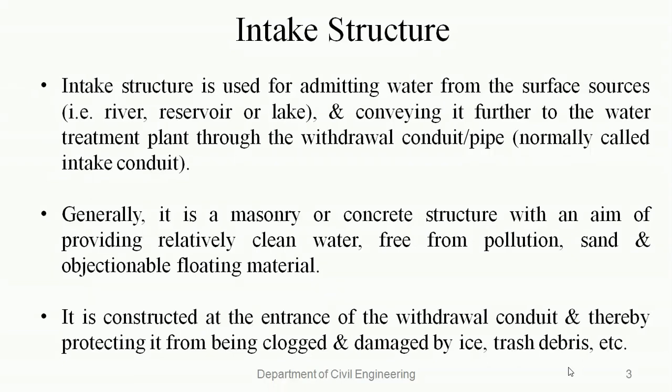After collection of water, the next step is to convey it further to the water treatment plant with the help of a withdrawal conduit / pipe, which is also known as an intake conduit. An intake is generally a masonry or concrete structure constructed with the aim of providing relatively clean water, which is free from pollution, sand, and other objectionable floating material. Intake structure is constructed at the entrance of the withdrawal conduit, as a result of which it protects the withdrawal conduit from being clogged and damaged by ice, trash, debris, etc.